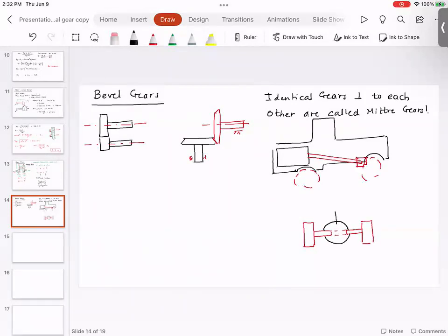So then you have the prop shaft that is coming in. The prop shaft will have a bevel gear. And here, there will be two bevel gears. And this is called the differential. Depending upon the type of configuration, you can have a rigid differential, you can have a limited slip differential, and there are various options. If you look at a rear wheel drive vehicle, you will see this big pumpkin at the end, and that is where that bevel gear assembly is located.